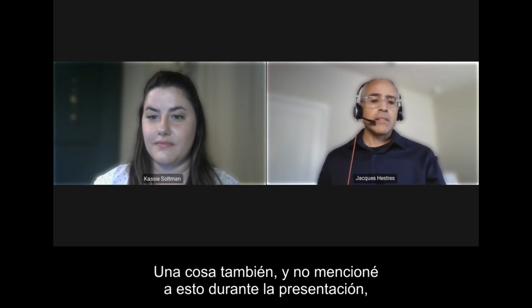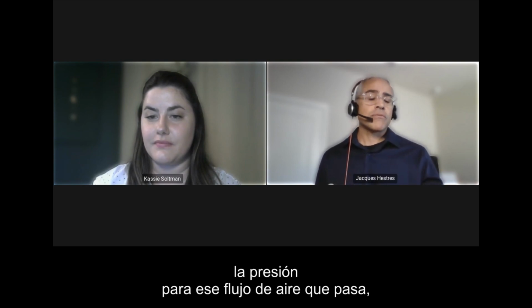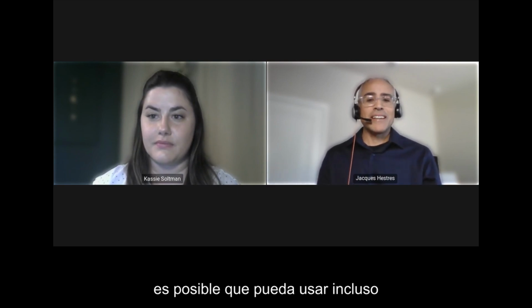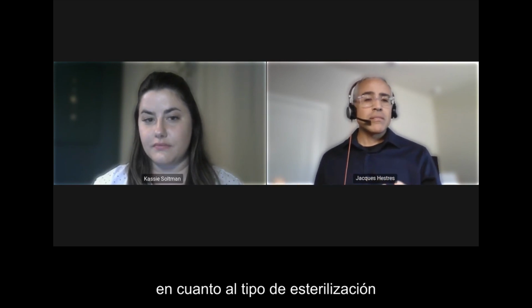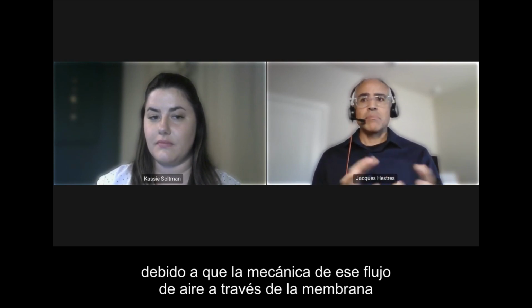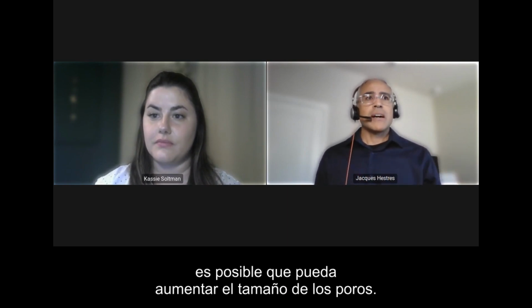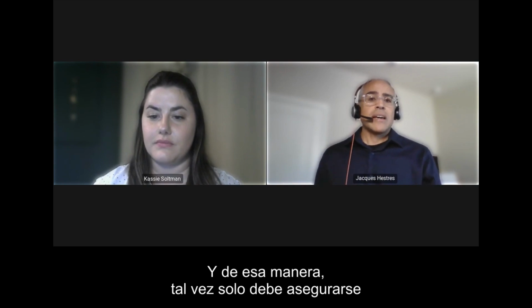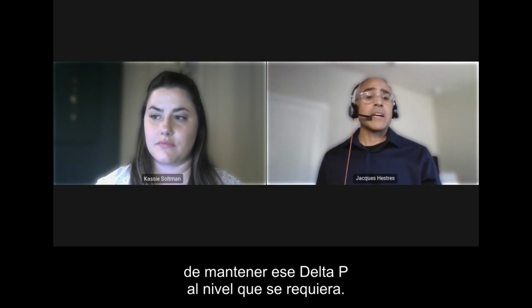One thing I did not allude to during the presentation is that, depending on the pressure for that flow of air coming through, you might find that you could use an even larger pore size than just 0.2 micron. 0.2 micron membranes are for sterilization where you're filtering liquid, because the mechanics of the flow of air through the membrane differ a bit as compared to liquid. You might find that you can go higher on that pore size, just make sure that you keep that delta P at the level that you require.